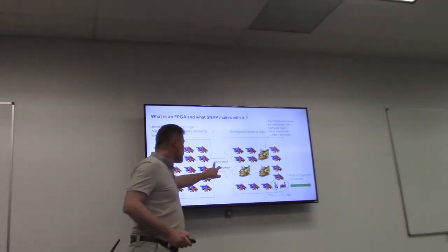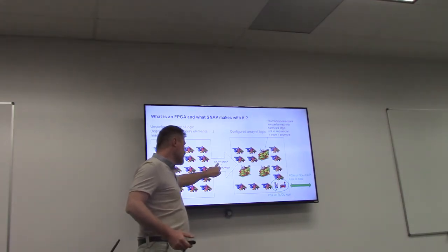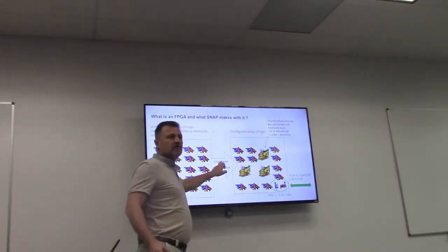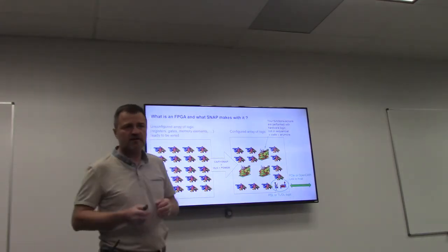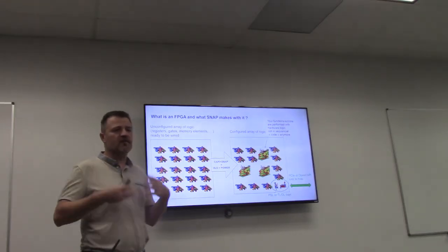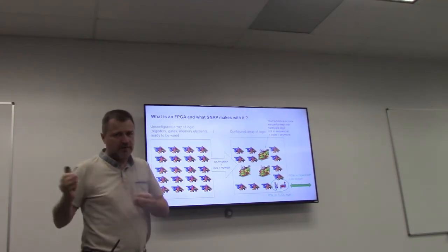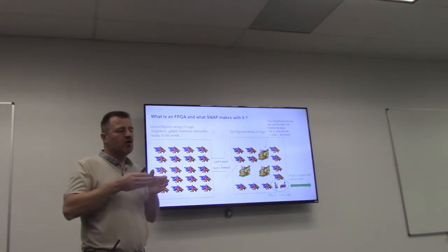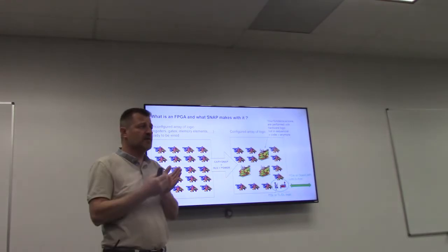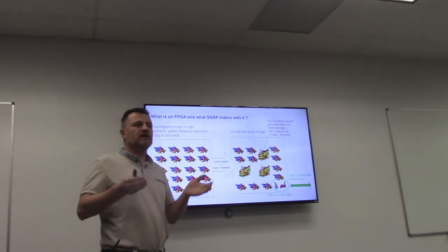The advantage of my presentation is that we are taking several technologies. The first technology is Power. The second one is CAPI. CAPI on Power, as my colleague has spoken a little bit about, is a very fast link. The goal in P8 was to establish a new link. In OpenCAPI it will be independent of PCI Express, but the goal was, on PCI Express, using the hardware to make sure that a card recognized by the system at power on is no longer known as a PCI card, but can be known as a CAPI card.